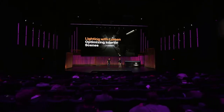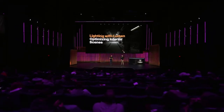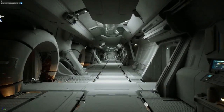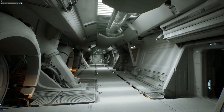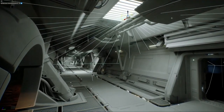Thank you, Jacob. Okay, so next we'd like to touch on how we optimized our Lumen lighting setup to carefully balance the trade-off between visuals and perf. This clip of the corridor lighting demonstrates many of the techniques we used on the rest of the ship. We're mostly using a combination of emissive planes in tandem with real lights. Most of our lights and static meshes are non-shadow casting, and you'll see why that is on the next slide.